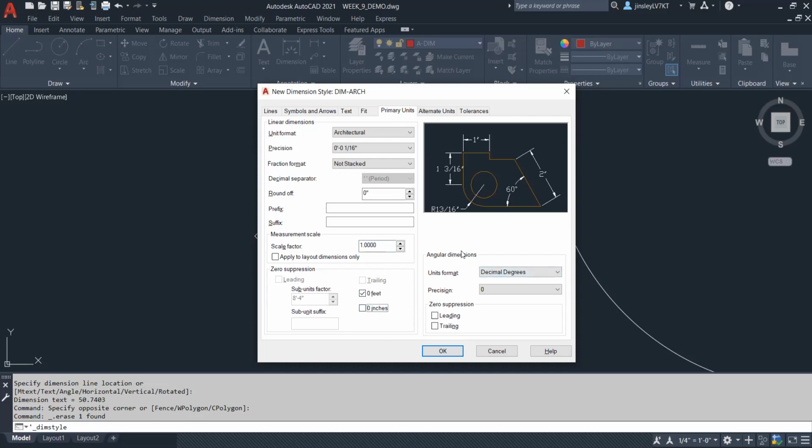Okay, angular dimensions. We can report to 2 decimal places. Even if on site they're just going to get as close as they can, there is a lot more technology available for measuring angles these days, and they might even have access to survey equipment. So we want to try to be as precise as possible when it comes to angles.